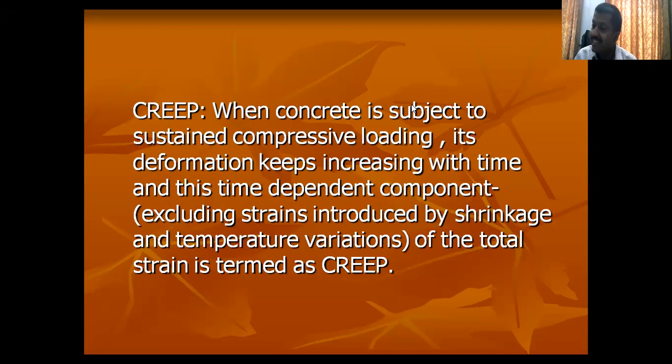No. The technical reason is that the concrete is weak in tension and it is strong in compression. So just to improve the tensile strength of your concrete, we are going to use the reinforcement. Okay, because the reinforcement you are not going to compress it.